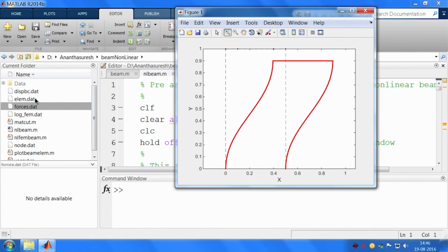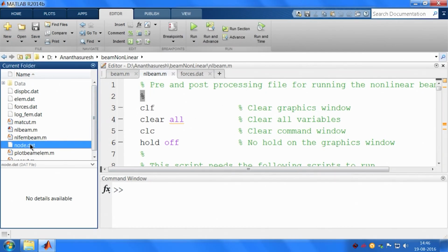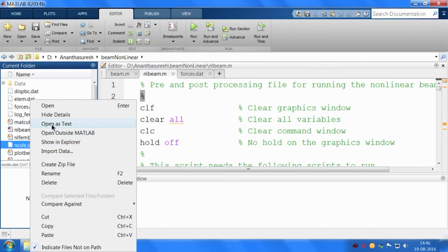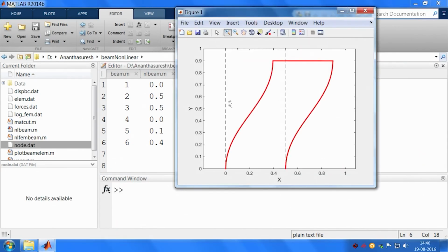So in order to get a little bit of experience for that, let us actually try to modify it right here. So let me open these, so you get some experience of doing that. Note that that has 6 nodes. Now I have to add a few more nodes. So I am going to add 7, 8, 9 at the bottom, that is, let us look at the figure. So I have this original one, I am going to have 3 more nodes here, one here, one there, so that I can have this vertical beam and 2 rigid blocks.